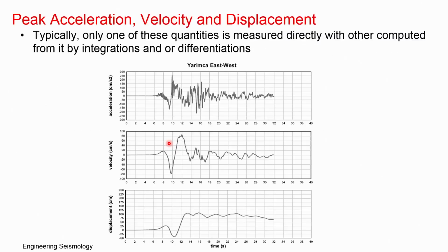As we have seen, each component of the data can be converted into three forms. From here you will observe a peak. Peak means the absolute value, without sign. Among these, whichever is maximum is the peak acceleration. Similarly, whichever is maximum is the peak velocity, and similarly, whichever is maximum is the peak displacement. So, you can directly see the waveform data and get the values.